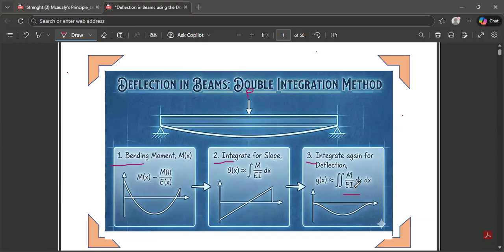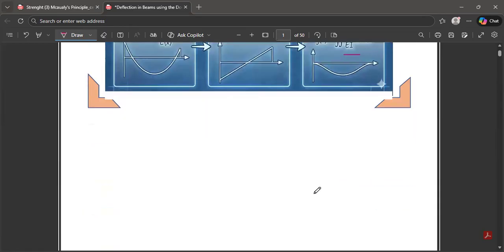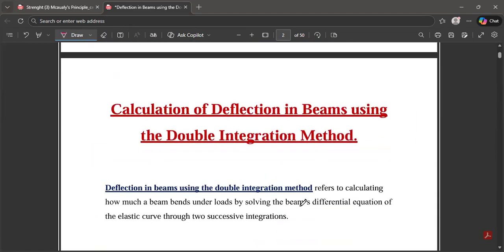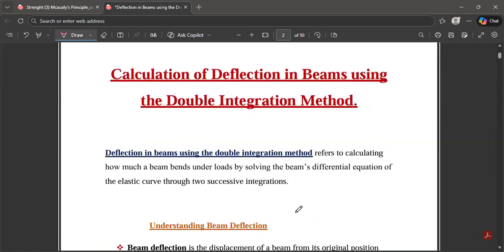Also, deflection in beams happens because the beam bends under transverse force, like point loads, distributed loads, or even moments could also cause the deflection in the beam. In simple terms, it's how much the beam sags or bows when carrying weight. So if the beam is not designed to carry that weight, you are surely going to meet uncertainties.